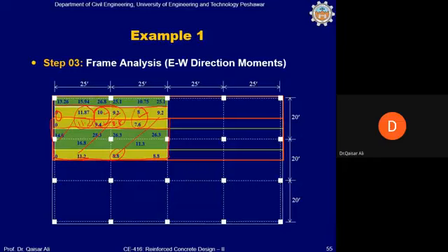Okay. Coming to the column strip of exterior frame. Column strip of exterior frame is these values. These are single values. For every value, negative, positive, negative, these are two values, so we will select the maximum, 26.8, positive and negative values. So we'll select this just like a bending moment for the beam design. Okay, 13.26 is the bending moment per unit strip width. We will multiply this by 12, and by trials we can design for this. Okay, now the column strip of the interior frame.